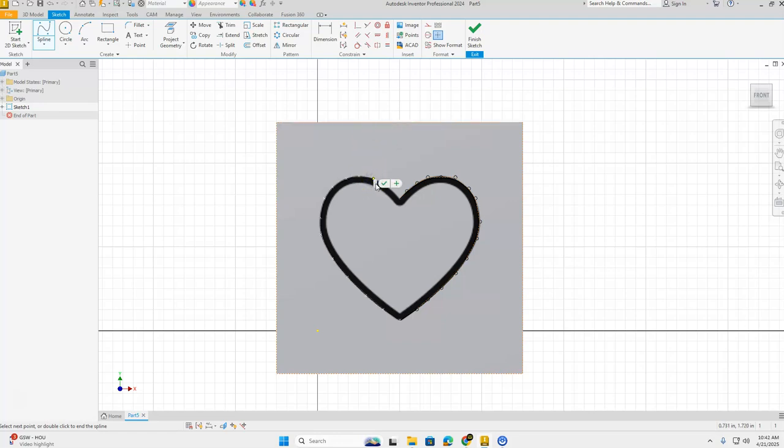When I get towards the center part of my shape again, one more to go here, find my green dot where I started. Make sure you're on a green dot so we have a closed loop for our image, and click to select it. Now is when I'm going to click that green check mark for OK. You can see that created my spline. My spline's going around half on each side from where I continued it, and my cursor is back to the pick tool. I'm not holding the spline tool anymore.